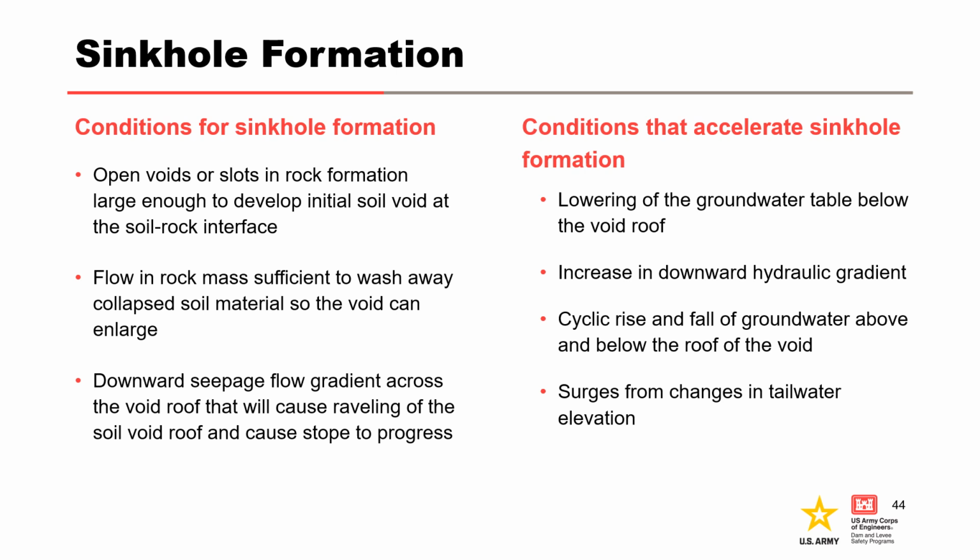Now, some things that can accelerate sinkhole formation include lowering of the groundwater table below the void roof, an increase in downward hydraulic gradient, cyclic rise and fall of groundwater above and below the roof of the void, and surges from changes in tailwater elevation.